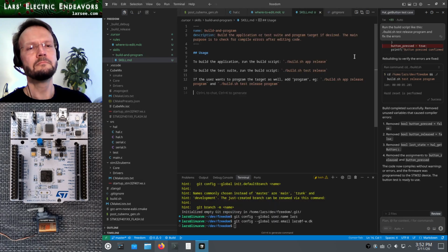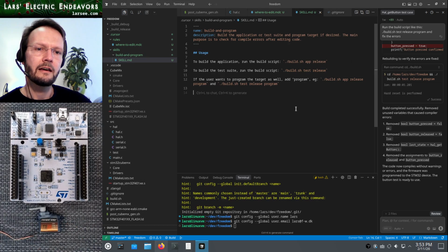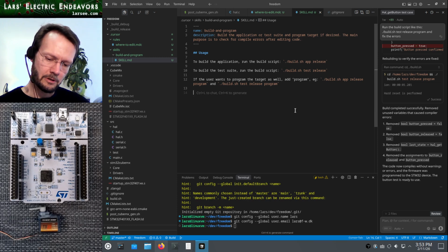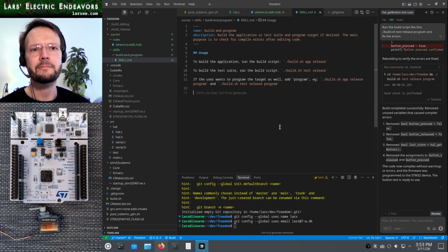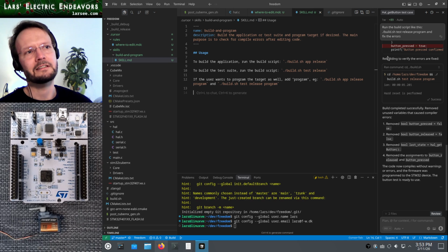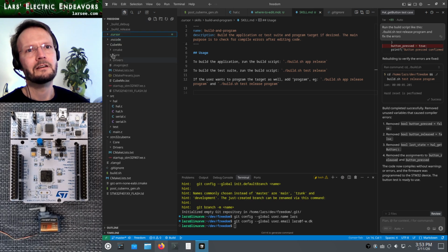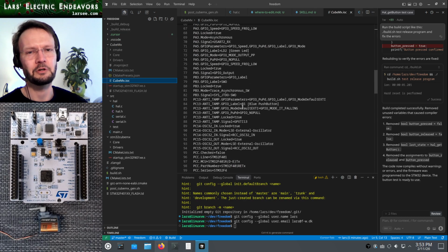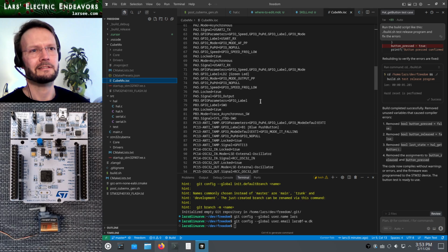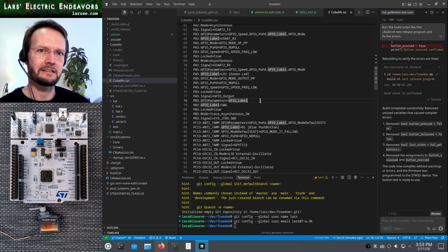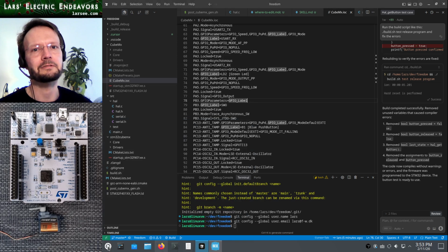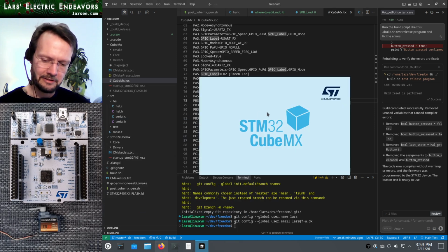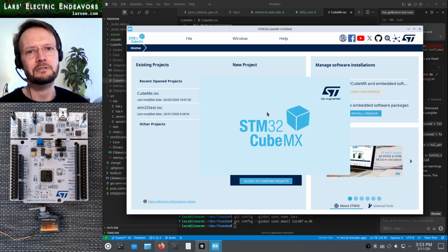So, okay, armed with that, it's time to start the real task of today. And the first thing we want to do now is we want to configure one of the I/O pins on this chip to generate the PWM. And I actually tried to ask the AI to do this for us by going in and modifying the CubeMX file. It did not work. So at least at this point in time, it's still something you have to deal with yourself, and you still need to have some knowledge about hardware and about the architecture of this chip to make this configuration.